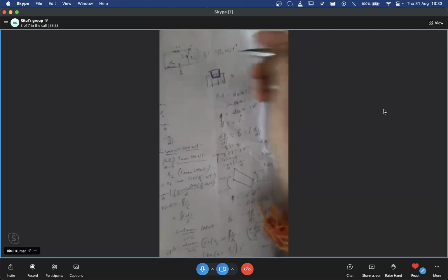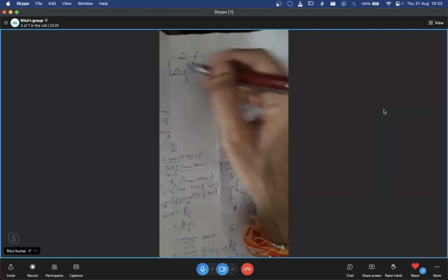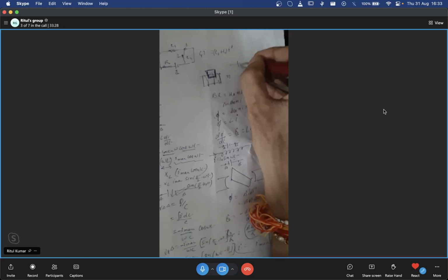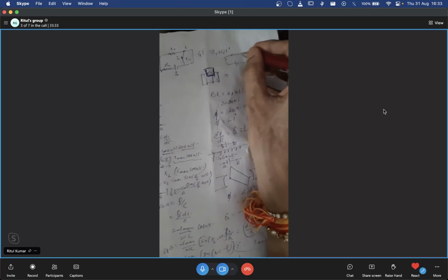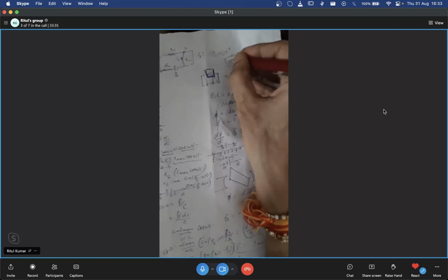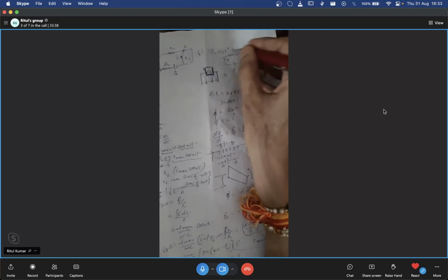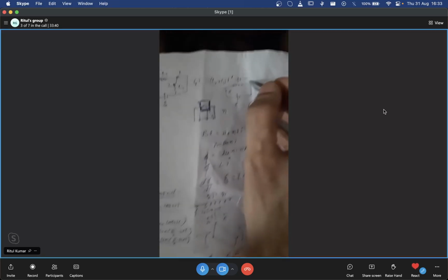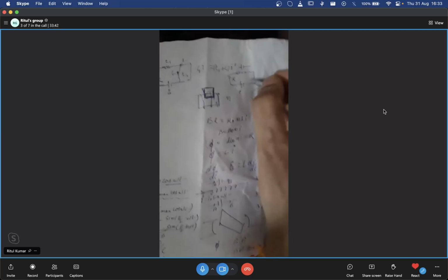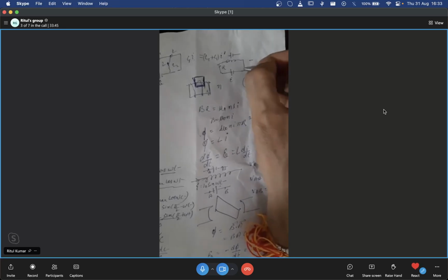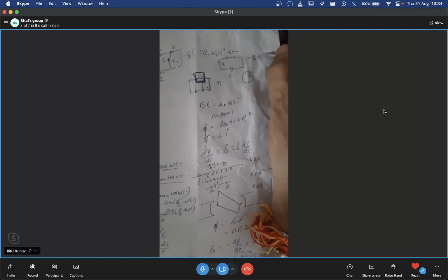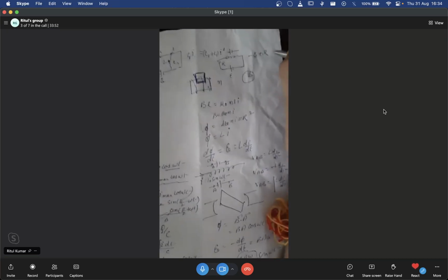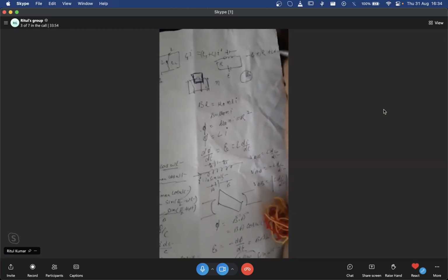Now, to what you were saying, I'll come to this equation. If you want this problem to be solved, we'll be solving it. But before that, charging, discharging. So charging, as you said, we are taking charging. Now tell me, I will write KVL. This is E, this is R. Current is increasing. So L dI by dt in this direction. Agreement? Okay, I write the KVL equation. What will it be? Minus of E from here to here if I go, minus of E, VAB, plus of IR, current this way, plus of L dI by dt is equal to 0. Do check.